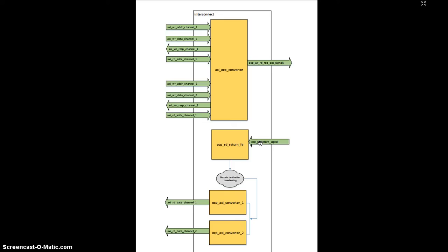As you know, we have two masters, and out of the 16 tags possible with the 4-bit wide tag in every interface, the first 8 tags are assigned to master 1, and the second 8 tags are assigned to master 2. In other words, all the interface tags in the master 1 interfaces will be between value 0 to 7, and the tags used by the second AXI master will be between 8 to 15.